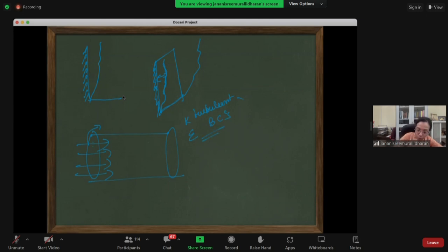So you will have to say my K is governed by I, epsilon is governed by some C mu, L factors and all that. So you'll have to calculate I and L. The length scale is the length scale of your domain. So here you're going to inject and give a turbulent boundary condition at the inlet.